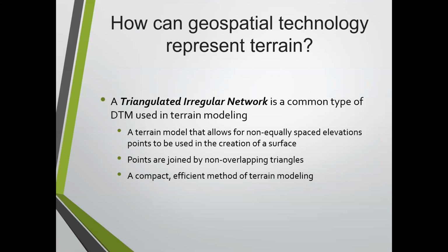And one of the draftsmen at our work made the point to me multiple times that you don't necessarily need the break lines; they just orient the triangles in the proper fashion. Because he'll draw smaller sites without any break lines in them, as long as you don't have a lot of change in topography. Right. It starts to be a complete pain. Because what will happen is, I think, Ben, you're going to get 80% of it correct, but 20% of it can be off.